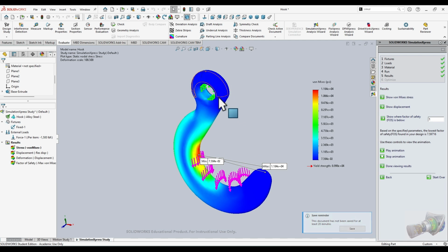So doing this stress analysis, we can tell that by loading this up with force, as we apply a heavier and heavier load to it, the part of the material that's going to be the most stressed, the part that's the angriest, that's getting ready to fall apart the quickest, is right here. And that makes the most sense, because if this was real and it was a metal hook, you could imagine that if we put a bunch of weight on it right here and held it perfectly still up here at this rigid point, it would actually start to bend right here at this elbow. So that's actually where it's feeling the most stress inside of the object itself.